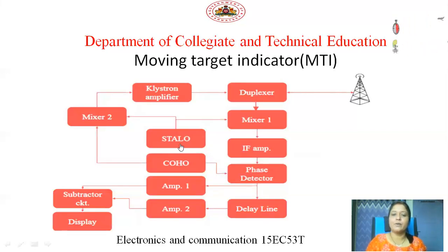And the stable local oscillator provides the translation in the frequencies at the transmitter and the receiver section here. Now this F0 and FC, this coherent frequency, is usually the same as the IF oscillator. Whatever the coherent frequency is, it is designed to match the IF oscillator here.